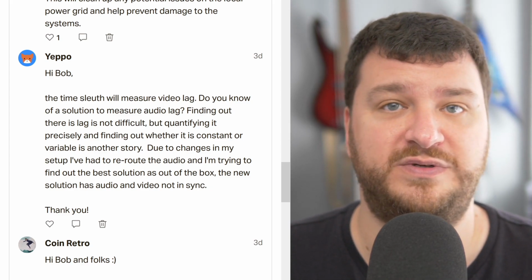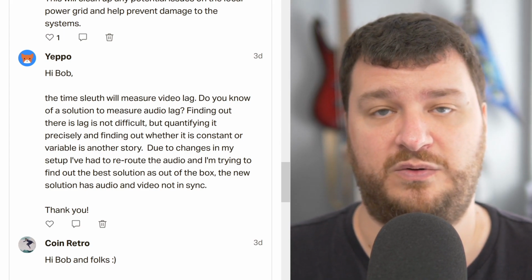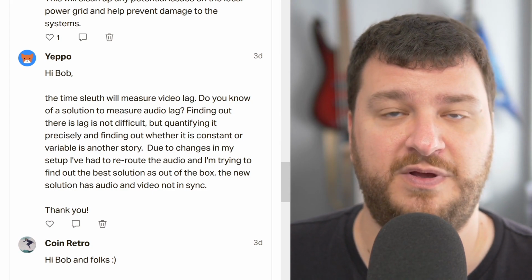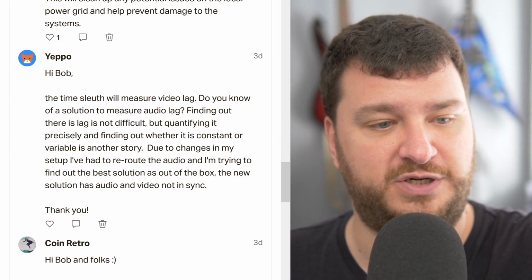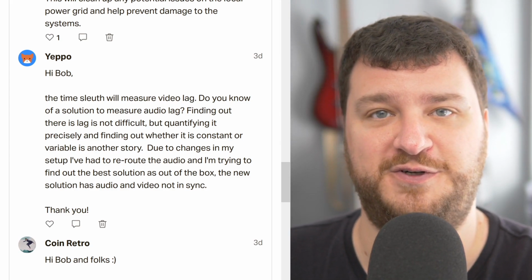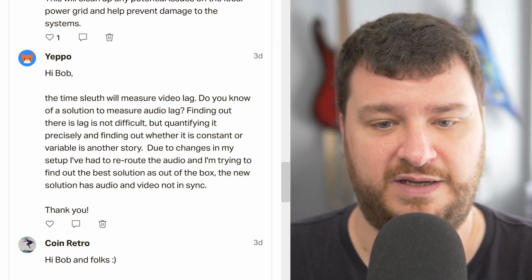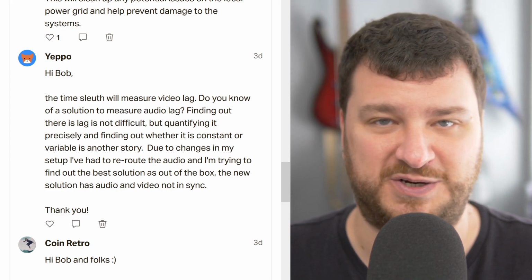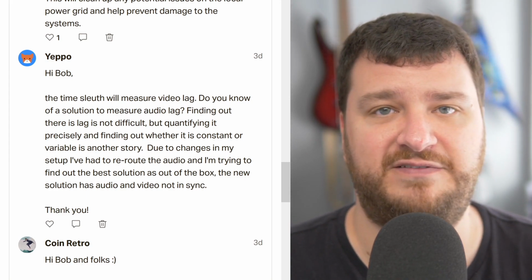And one thing that you could always do, if you have the ability to set up a camera, is the jump test, where you just jump in your favorite game and then slow the footage down so that you see when the character jumps and how many frames in the footage until you hear audio. And then just do this like a Sega Genesis directly connected to a CRT with speakers, and then do it again in your setup and see the difference. Maybe do it 5 times each.